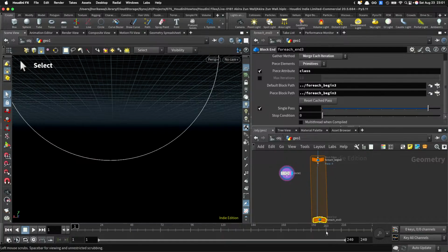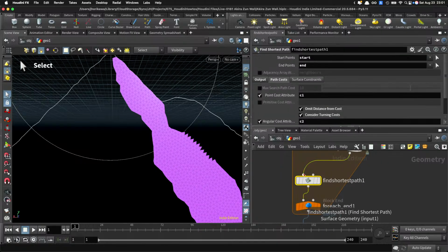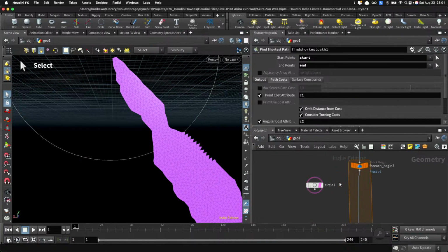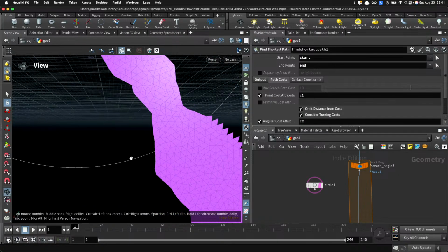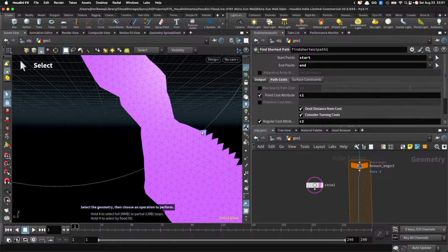Now, just cutting it as is not really clean. I mean, it doesn't really look like a crack. So instead of doing that, I'm going to use the similar process where I have created the edge for a crack. So meaning I'm going to use the find shortest path to create the cutting path. Okay, so to do that, what I would need is an intersecting point on the border somewhere around here, and intersecting border somewhere around here, and setting one of the points as a starting point and another point as an ending point, and create